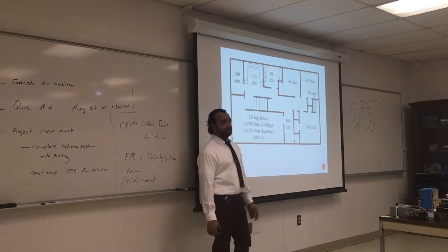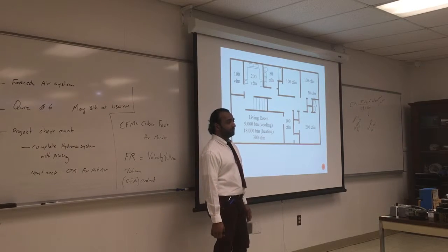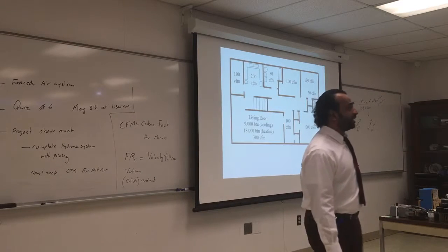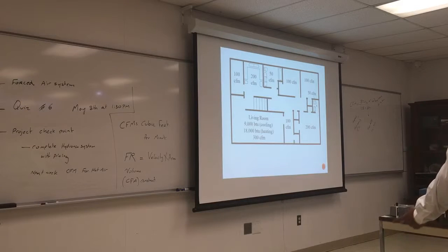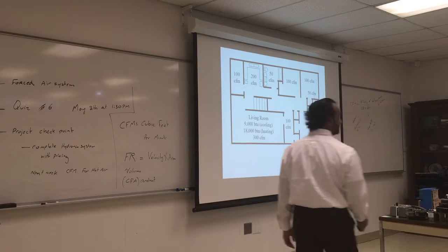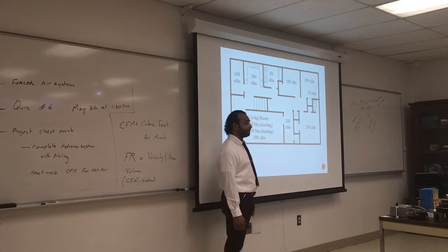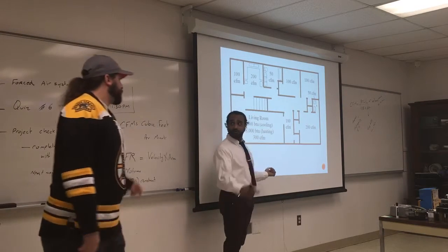So when we design the CFM, we want to use the BTU for both heating and cooling. Which one do we size? If you want to size the amount of CFM required for this room, am I going to use the heating or cooling? Heating. Heating, why? It's higher. Good.